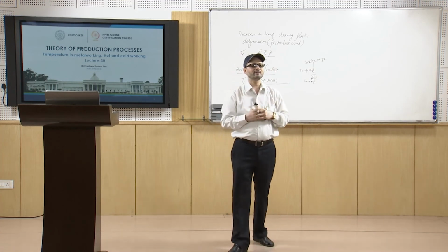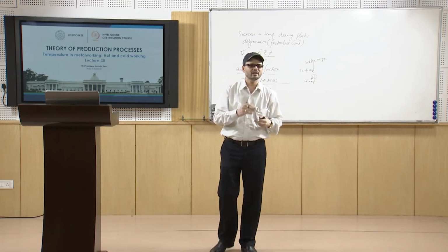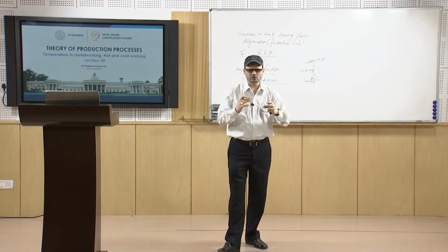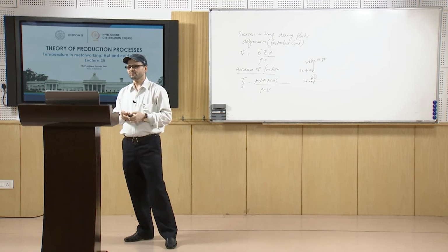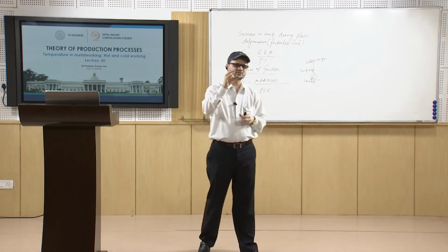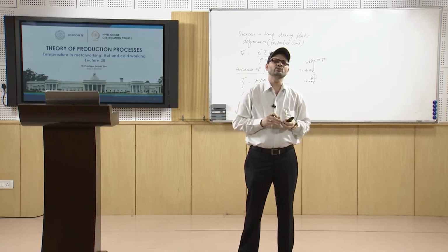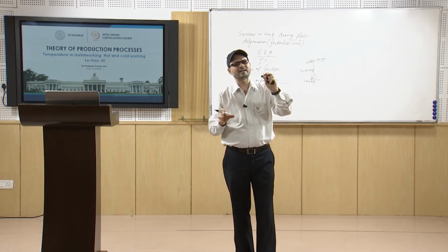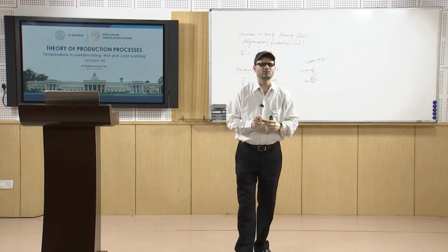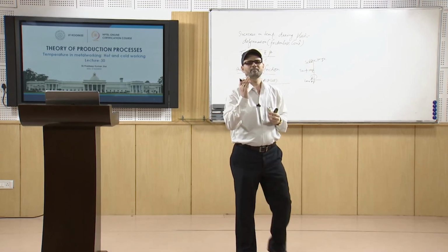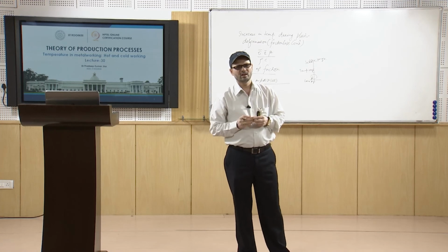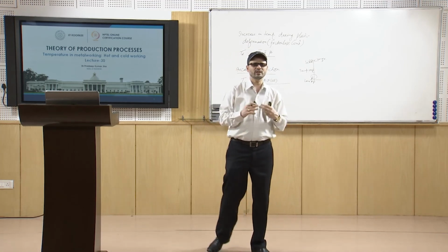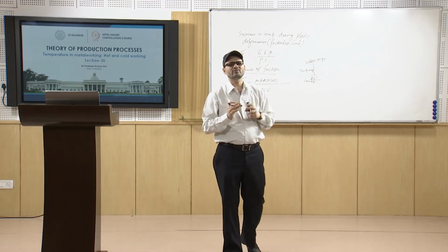You can have a degree of reduction, and you can also see the degree of strain hardening possible, and normally the practice is that you can control the hardness of the material in this cold work and anneal cycle. Whatever hardness you need, depending upon that: if you want the hardness to be high, then cold working should be the last operation, or if you want the material to be in a soft state, then it has to end with annealing. This way you can control the hardness or softness of the materials.